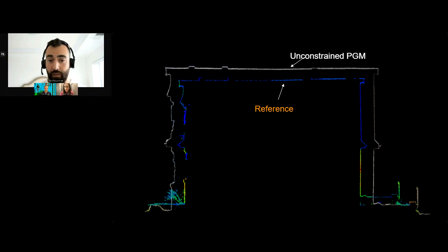But photogrammetry without controls is prone to this scaling error. This isn't a novel finding. This is very well known. So that's why we use controls when we can to reduce the scaling error. You can see this section from the side of what that scaling error appears to be. It's relatively accurate. The overall shape and size matches what the house looks like. It's just globally scaled up due to that unknown of exact dimensions from just camera images.